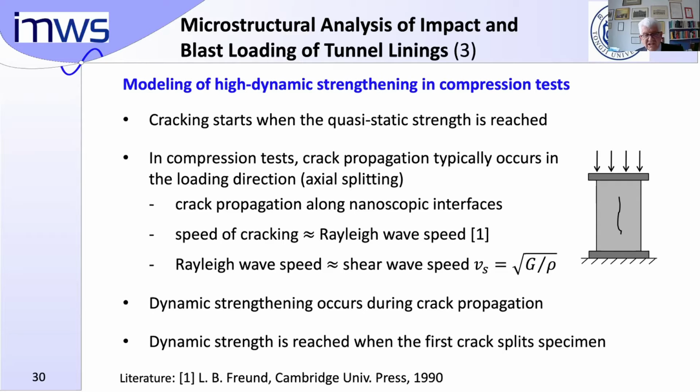Crack propagation takes place along nanoscopic interfaces. The speed of cracking is approximately equal to the Rayleigh wave speed, and the latter is approximately equal to the shear wave speed. Dynamic strengthening occurs during crack propagation, and the dynamic strength is reached when the first crack splits the specimen.